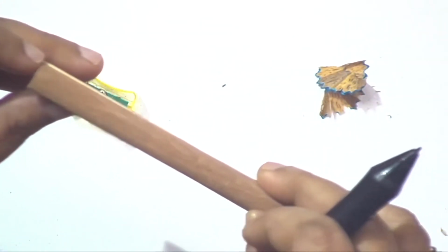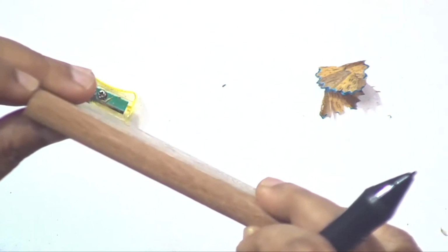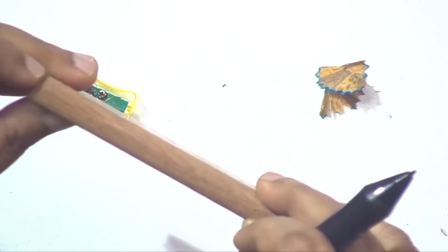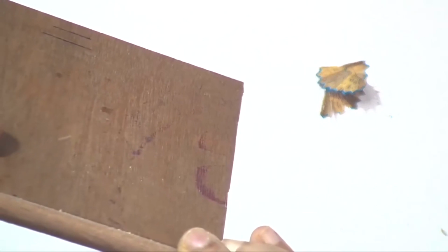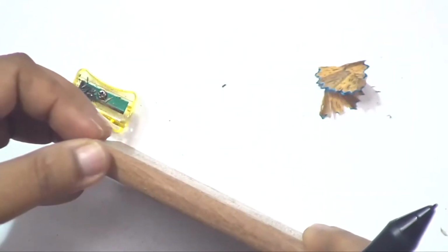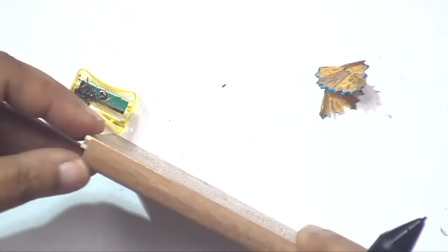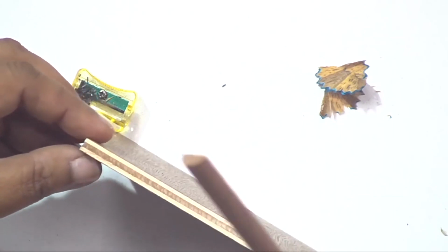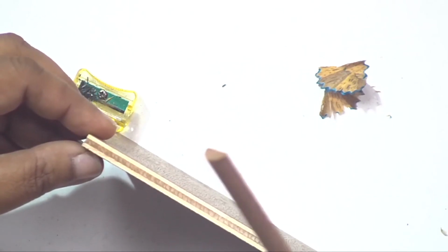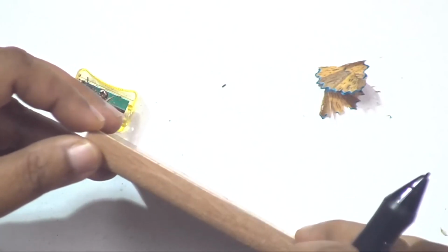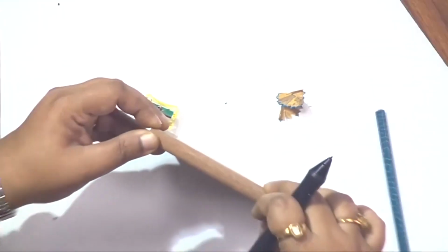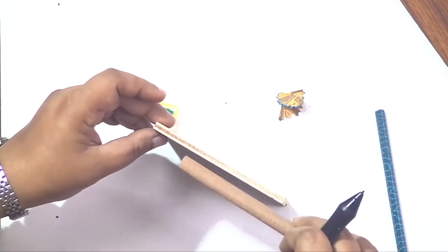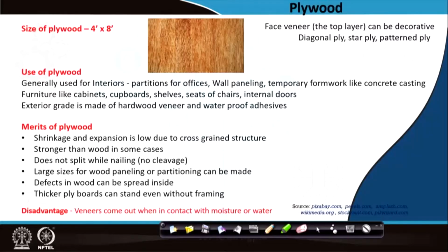So, once you finish this lipping with a good paint or a good varnish or a polish, no one can understand what it is. The edges are protected so that they do not come out, and cannot get affected by water, and this is made of pure wood. This is called a lipping, which closes or ends the edges. You need to add it at the end to give a neat finish and also allow the edge to be protected from moisture.